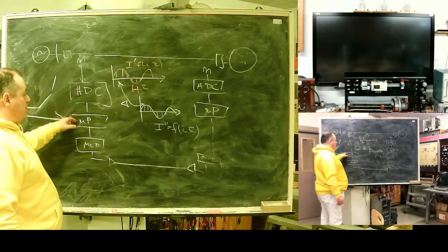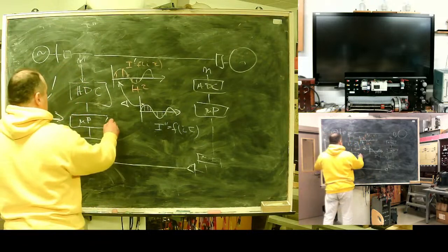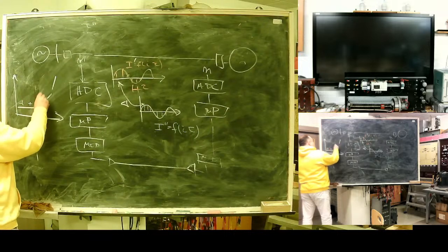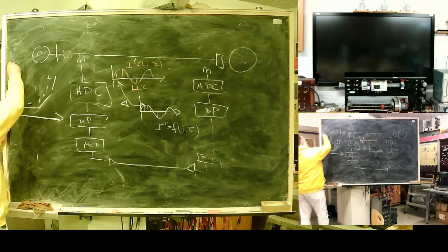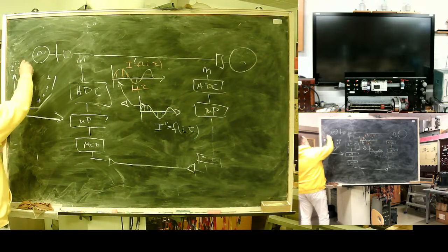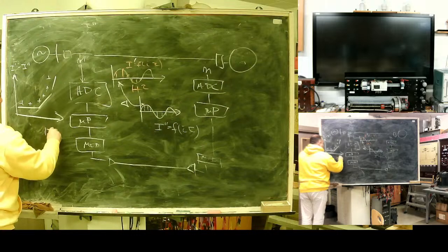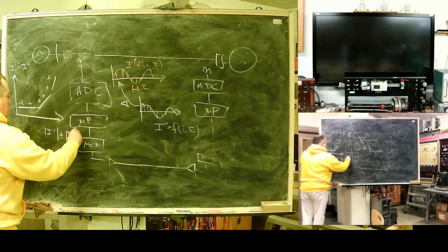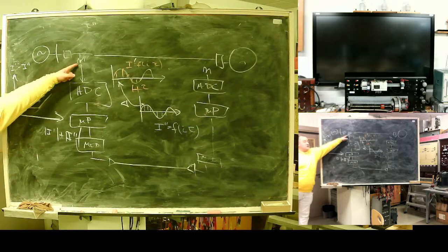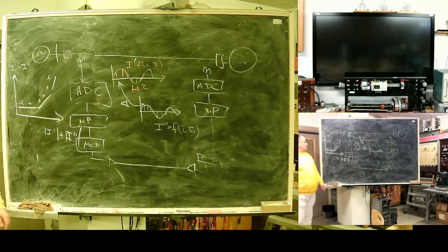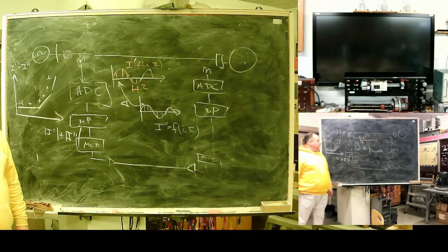So inside your processor logic, here will be I1 minus I2, I1 plus I2. Instant values. This stabilization chart needs to compensate an error of this transformer. Follow this characteristic and everything should be fine.